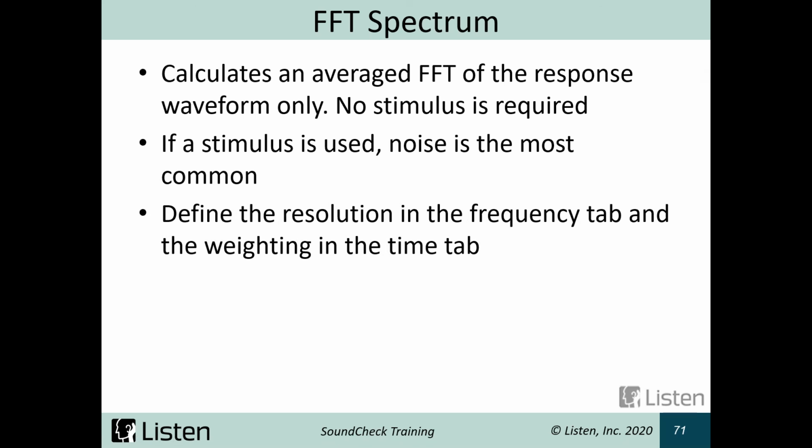The two tabs that are important to pay attention to, specifically for FFT, are the Frequency tab and the Time tab. The Frequency tab is going to be where we define our resolution. In the Time tab, we're going to define our weighting and windowing.